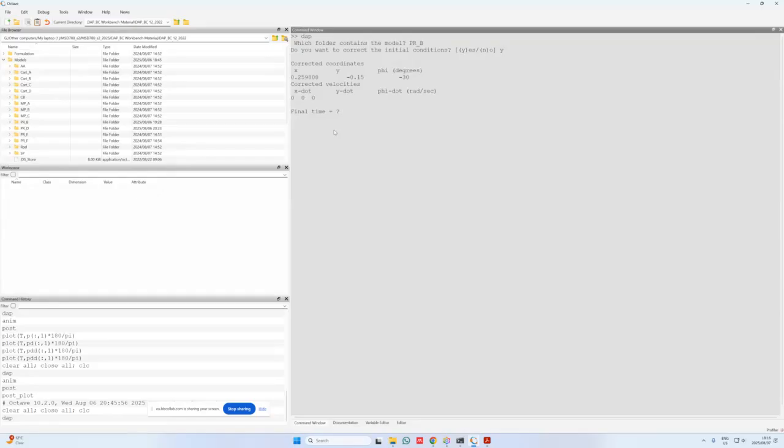All right, so next up, it then asks for a final time. So for how long do I essentially want to run this simulation? I'm going to type in 3, so for 3 seconds. And then I need to give it a reporting time step. With regards to this, it's always good practice to start with a coarse reporting time step to look at the animation.